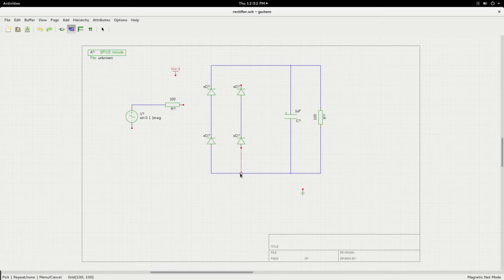You make the connection for the diodes too. The diode is a sub-circuit model. That is why we have an X mark, an X at the beginning. All sub-circuits will have X at the beginning. Then the source is connected to the center portion of the bridge, and we have the circuit in place.